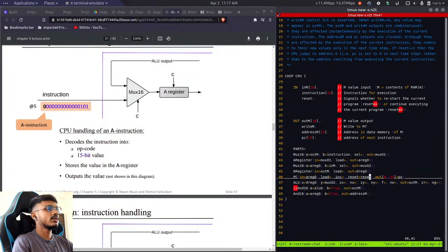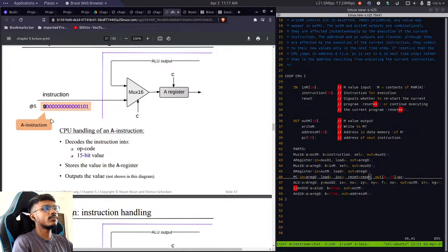So that means we can use this first bit from the instruction as this control bit. If it is 0, no, we should first negate it, because if it is 0, we want to load this instruction directly to the register. Not directly, but we have to pass, well, if it is 0, it doesn't matter, we can pass it directly inside this A register, right?